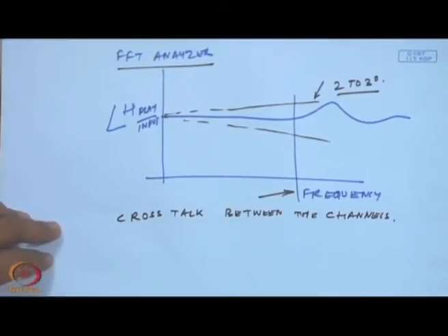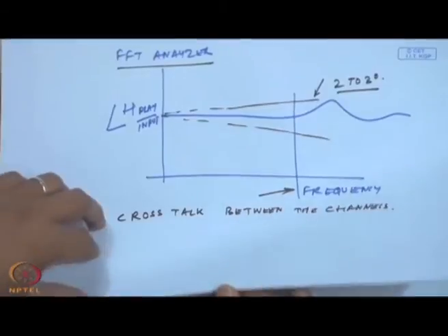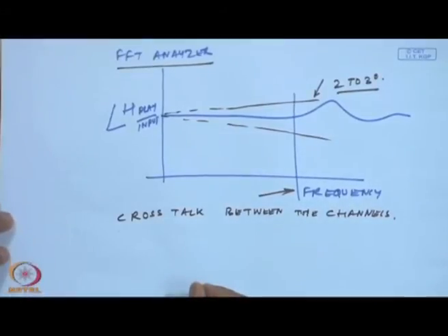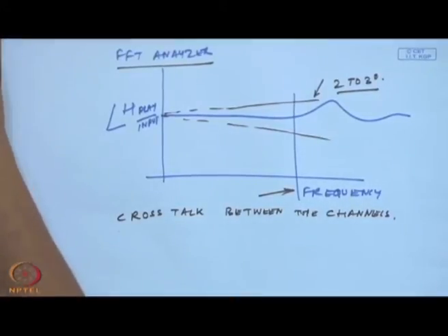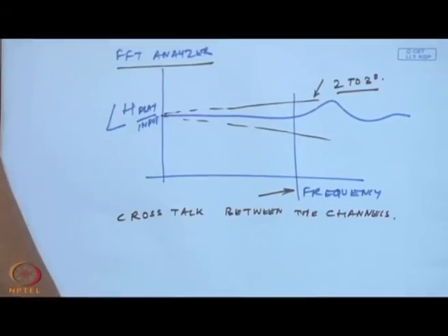Now, once we have recorded this signal, we also need to transfer the signals, and usually the signal transmission rate depends on the number of channels multiplied by the acquisition rate and the resolution. The data transfer rate is given in bits per second, the acquisition rate in samples per second, and the resolution in bits per sample.